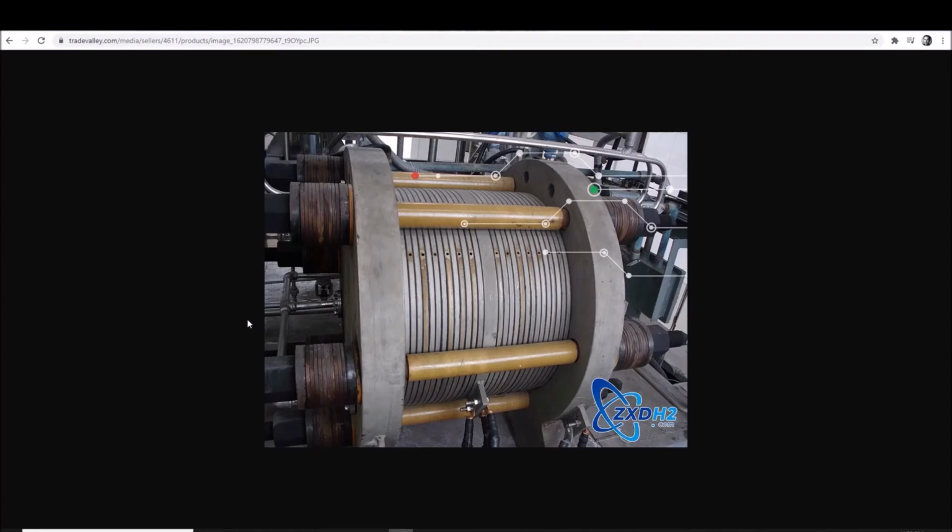most alkaline electrolyzers that I'm aware of use a bipolar cell configuration. So you can see here, you've got the current coming in, but it's not attached to each electrode. So you don't have a positive attached at the end of this electrode and a negative attached at this electrode. It passes through the electrolyte medium.